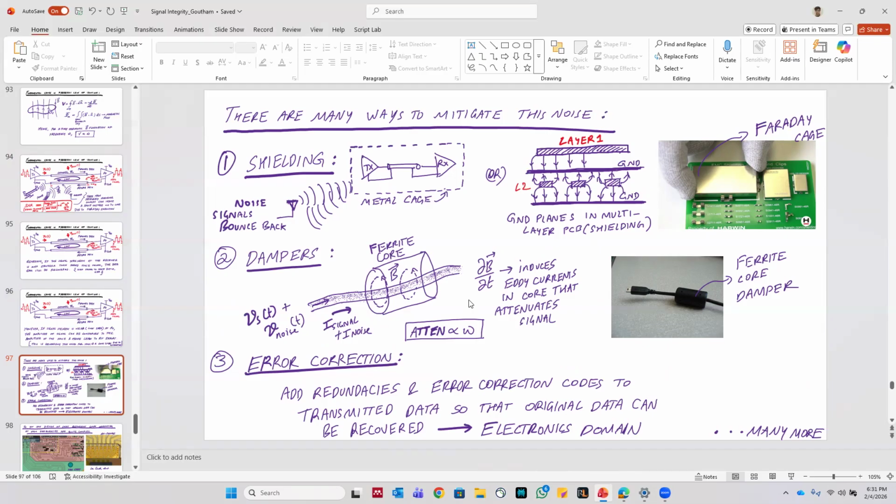If you remember a little bit about a Faraday cage, it need not be continuous. It need not be a direct shell of metal. It can also be a cage of metal, and it still behaves the same way. So rather than having a full shell of metal, you can have two ground planes, and if I connect the two ground planes by an array of vias on either side in the PCB, then I've created a cage that encloses the metal wires, and I prevent any EMI from being picked up.